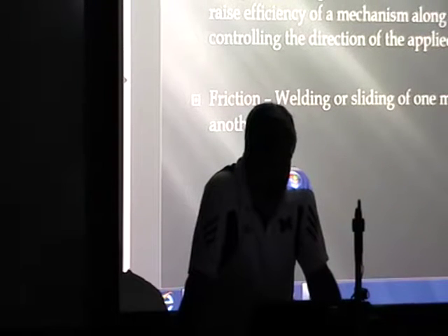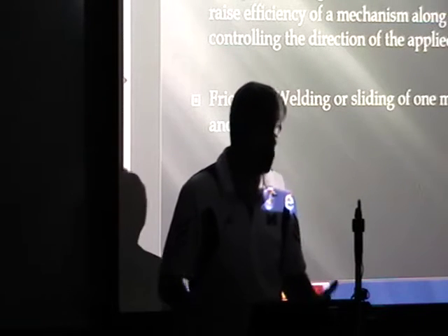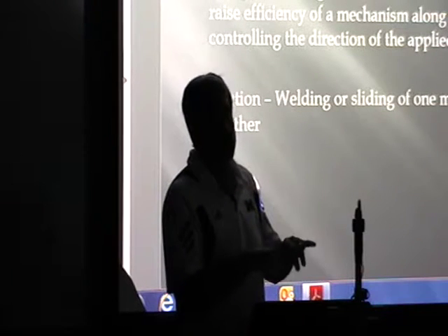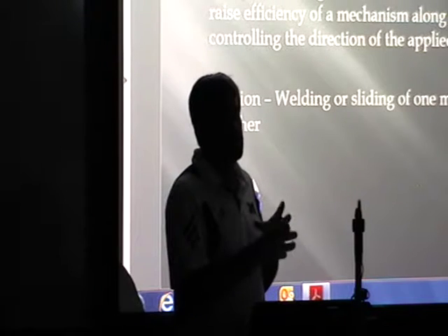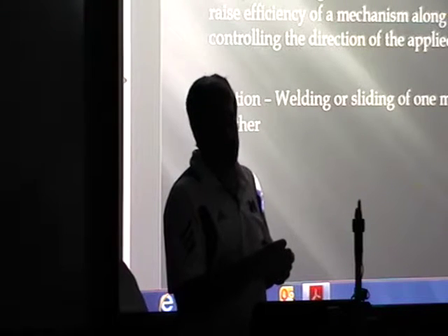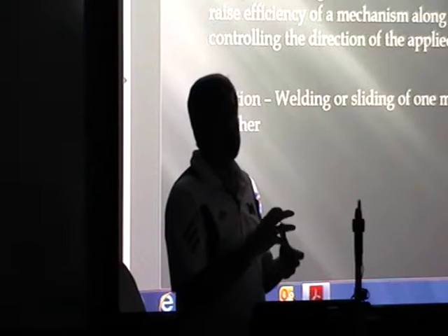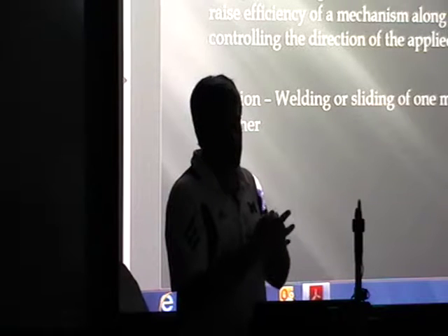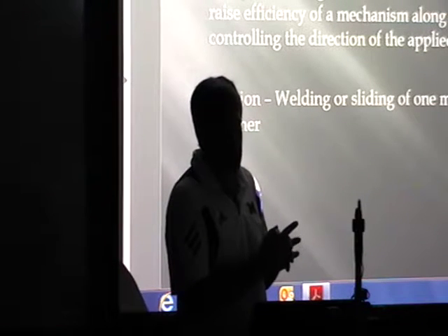The metal on metal can actually get micro welds if you're trying to slide metal on metal, or metal is rubbing. If you're trying to run a shaft through a hole with no bearing surface in there, you actually get micro welds, and it actually joins one metal to another. And what a bearing will do, it either puts a rolling element in there or it introduces a component of oil which will fill that groove and create a sliding surface with the oil.